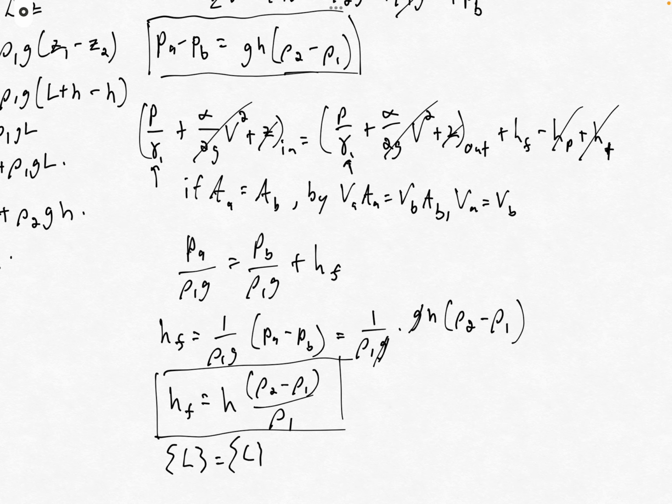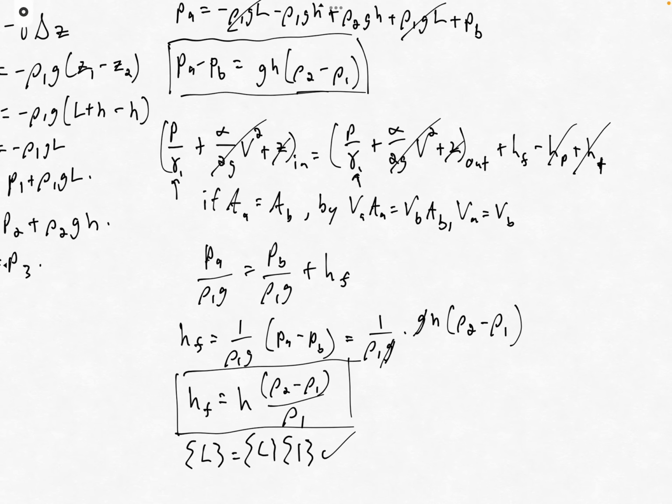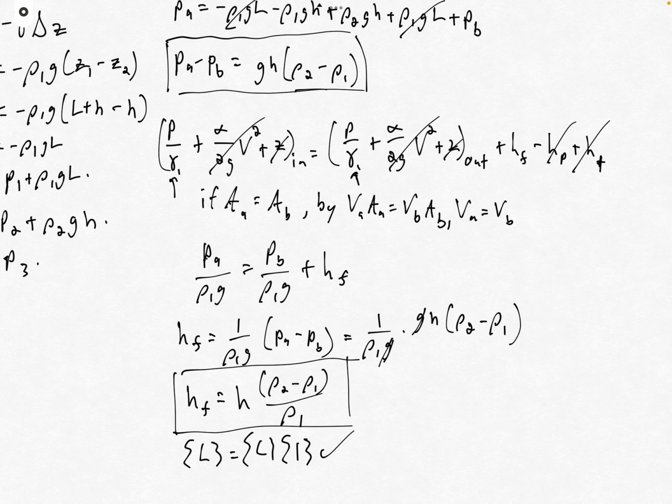And when we take delta rho, that still has the same dimensions as rho, and dividing that by rho means that we're just multiplying by something that's dimensionless. And so we have L is L, and therefore this expression at least is dimensionally consistent. So there we go. That was an example of fluid statics, but also how we can use that to learn something about energy balance as well.